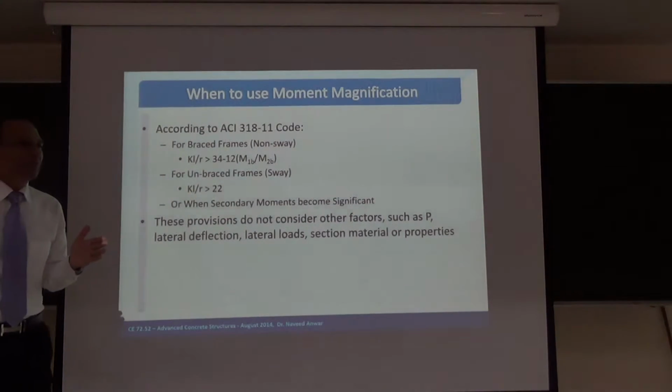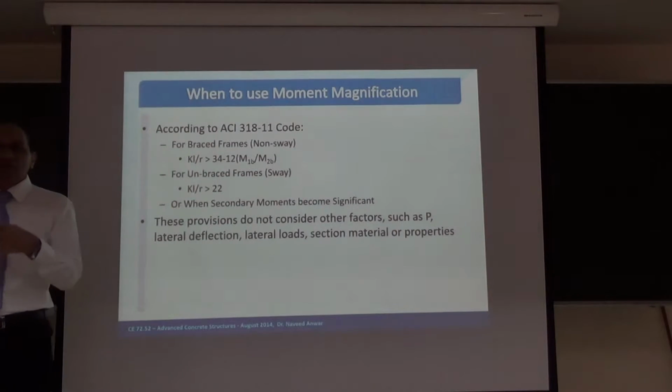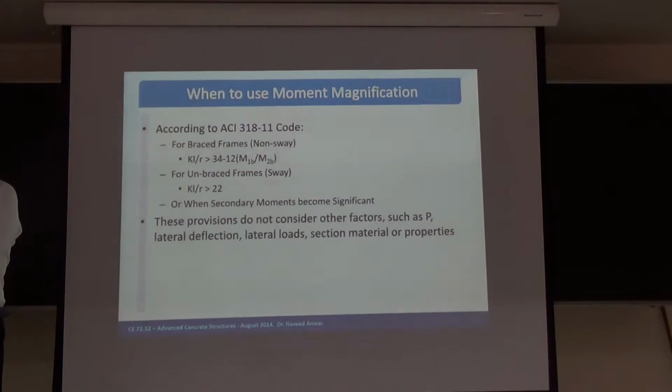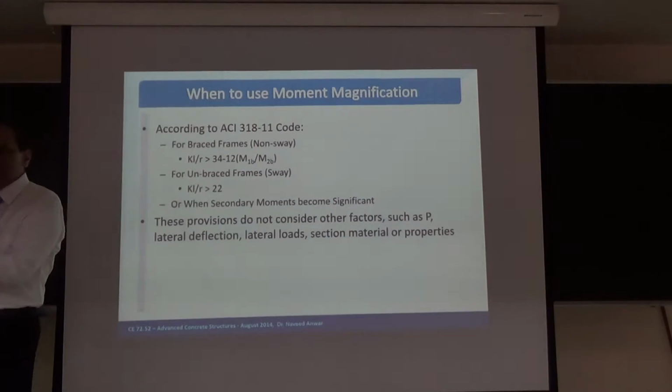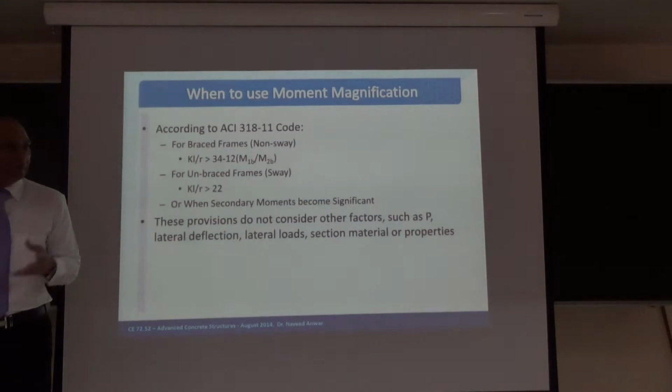It is just too big to be slender. For a 2-story building, the column size will be maybe 200 millimeter or 300 millimeter by 300 millimeter for the same 3 meter height. So obviously the column is likely to be slender because the building load is too small, so people make the column very small, sometimes only 250 millimeter, 25 centimeter or even smaller. So it becomes a problem.